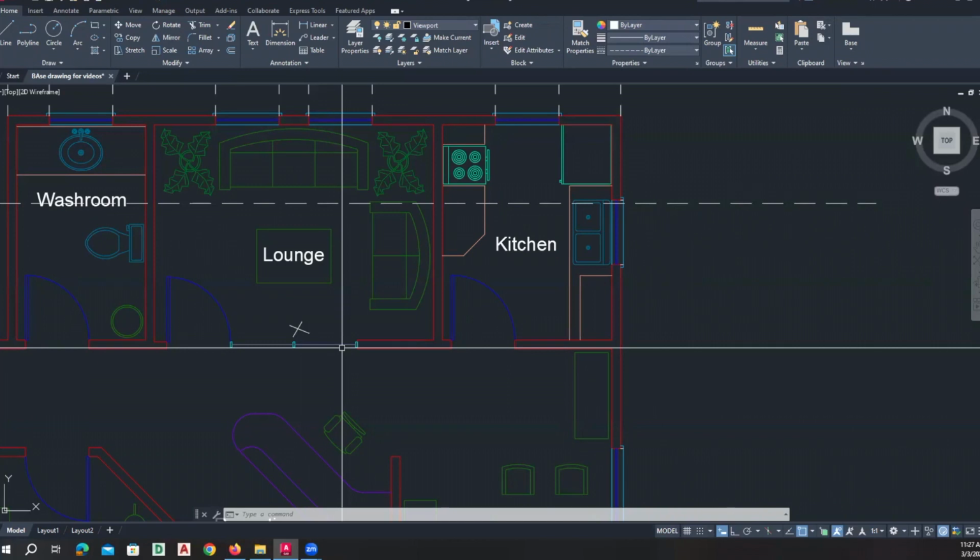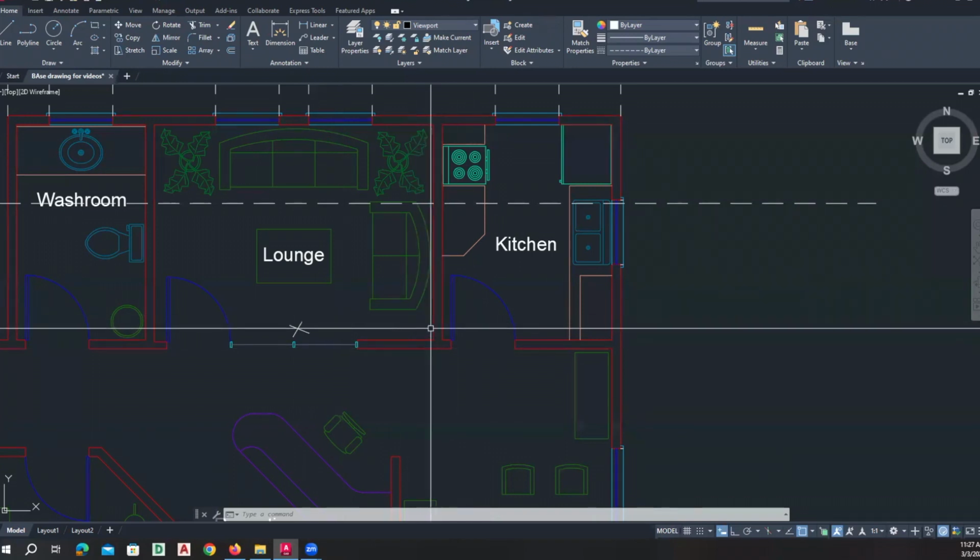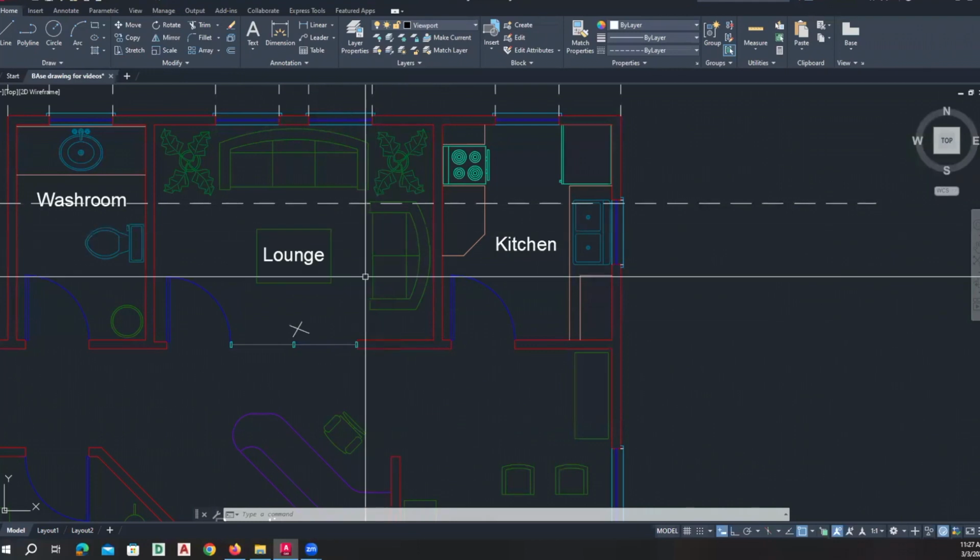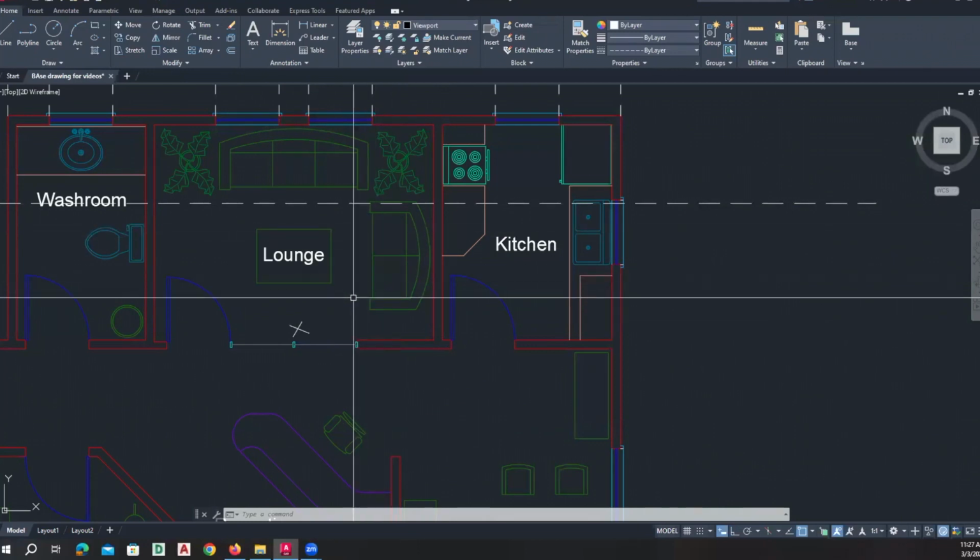And that is basically the same idea, right? The things that are closest to you will have more detail, but will also be clearer, which means they will have a darker line weight than the things that are further away from you. Things that are further away from you will be lighter and may have less detail, right? Things that you are cutting through, like let's say a wall, will still be the darkest line weights, similar to the plan, but certainly the objects that you see in their entirety will be based on their line weight, okay?